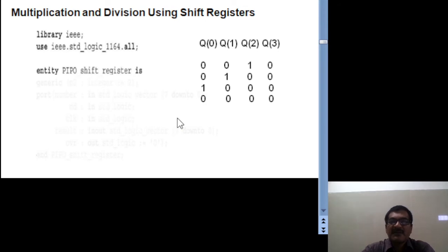Okay. So this is the first line in the entity declaration. After that, here generic of P2 colon integer colon equal to 2, that means P2 is declared here. P2 is an object which holds an integer type of data. That too, the value is 2. So the 2 is loaded in the P2 object.